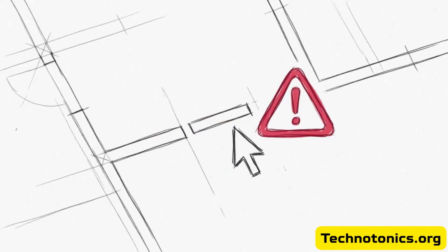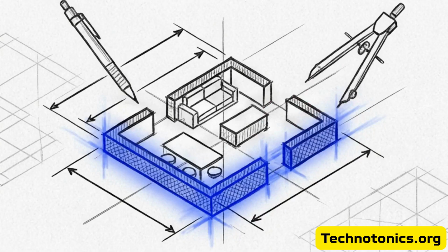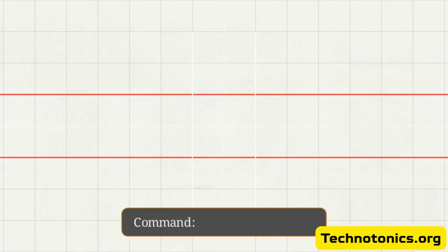The most common error here is clicking the segment you want to delete while forgetting to select the cutting edges that trap it. To avoid that entirely, use the double Enter shortcut. Type TR, press Enter twice, and the software automatically selects all potential boundaries. Now, clicking a segment instantly cuts it away based on the nearest intersecting lines.